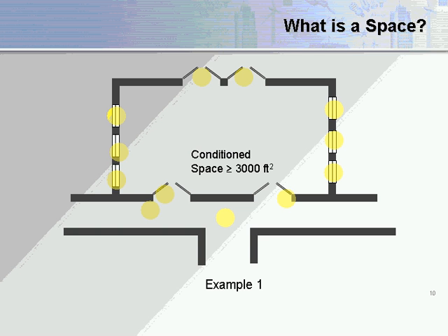The walls would be floor-to-ceiling height partitions. There probably will be a roof over there or a floor over the top of this to basically show that to be a fairly enclosed space. So by definition, from an ASHRAE 90.1 2001 standpoint, we could consider this area as space, and if this space were greater than or equal to 3,000 square feet, we would need a vestibule then off of these exterior doors.